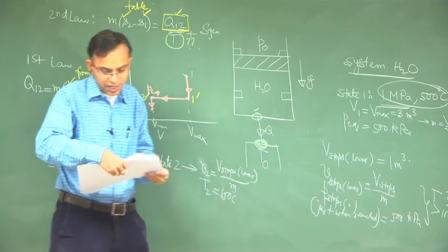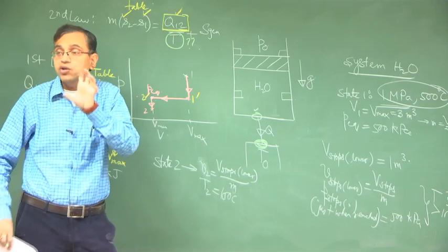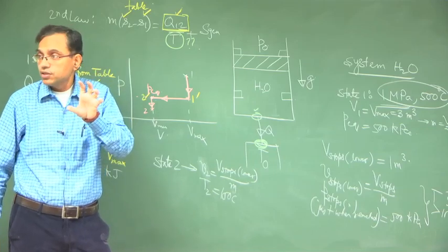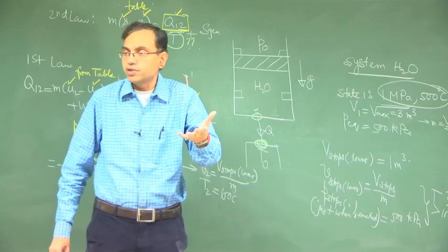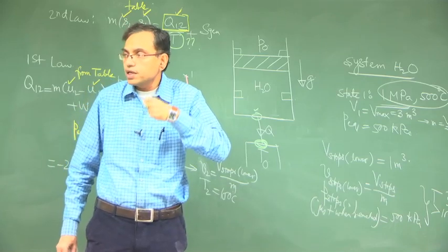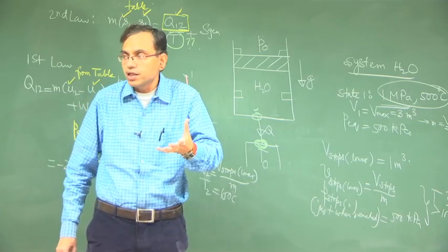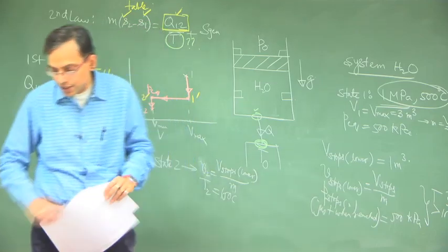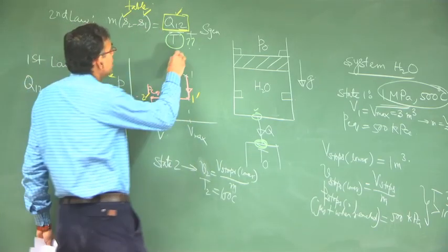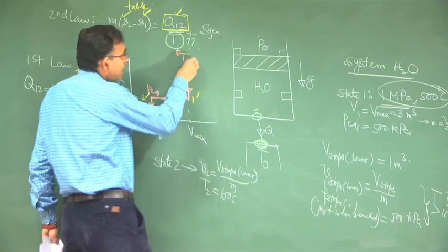So, here what is asked is find the total entropy generated in the process. Total entropy generated in the process means not just due to internal irreversibility, that entropy generated due to internal irreversibility plus entropy generated due to the external heat transfer, and that is why you have to substitute here T equal to T0, and that also in Kelvin.